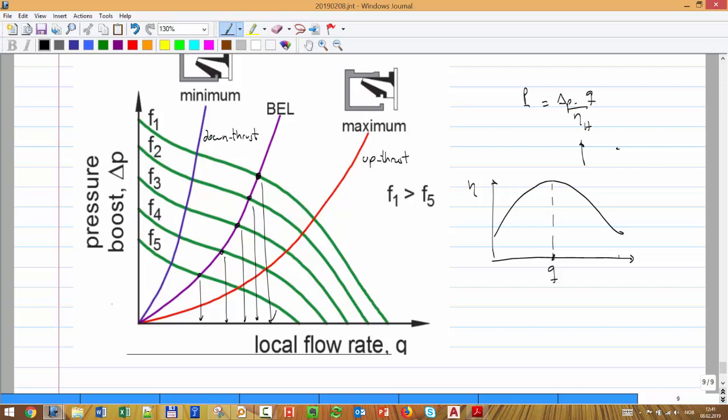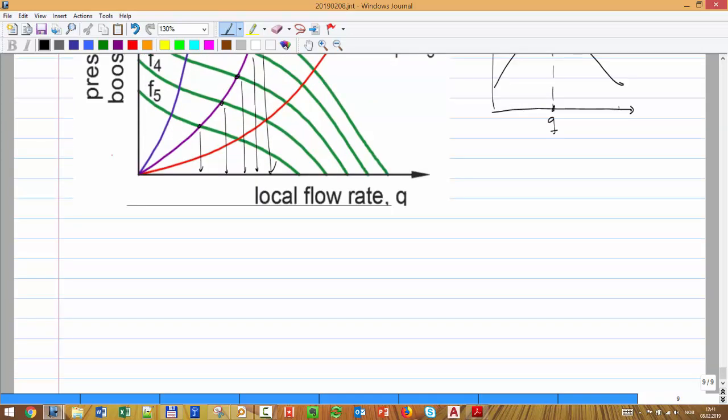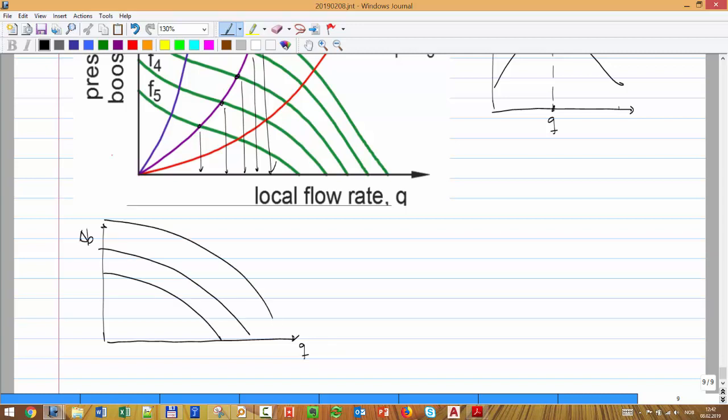So if you want your pump to have a long happy life, you should be between these two lines. That means that the area of the pump ends up being, remember we have all of these for different frequencies, F max, F min, and then we have these two other lines which look something like that. That means that the feasible area of the pump is actually this one.